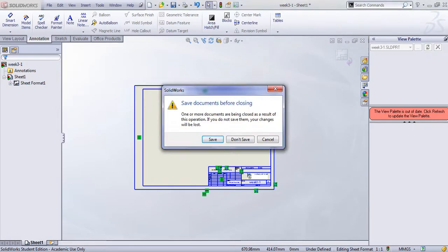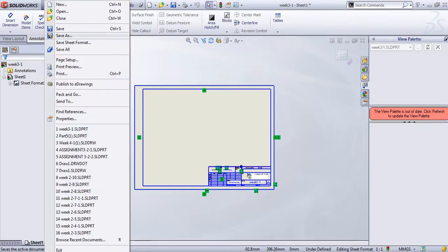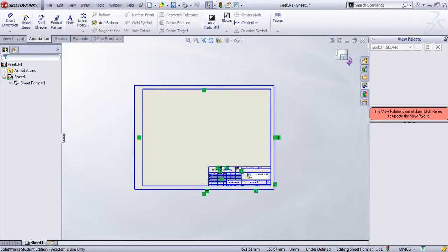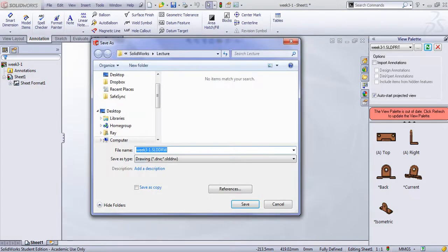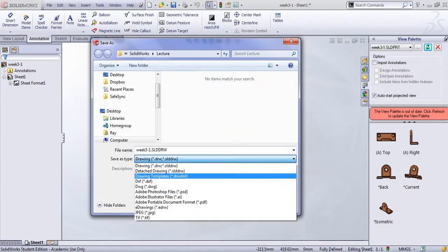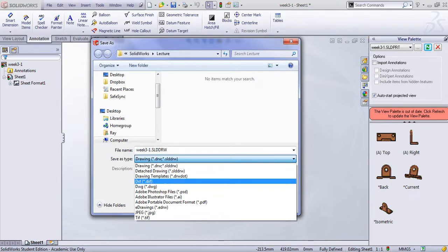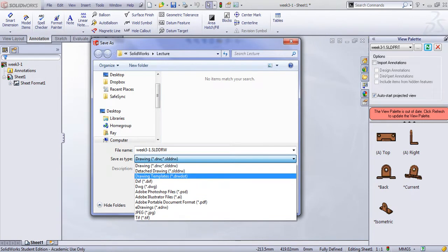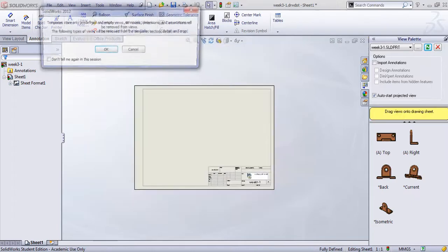And as a matter of fact, I show you what I did here now. And then, of course, you can save this one here. I can go here, save as. I finish this one here and I go save as, and of course I don't want to save as a drawing. I save as a drawing template here, and you can put a name for it. You can have as many as you want, and then let me just save it as drawing template here. I make it as number 2, even though it's not perfectly the one I want here. And now save.